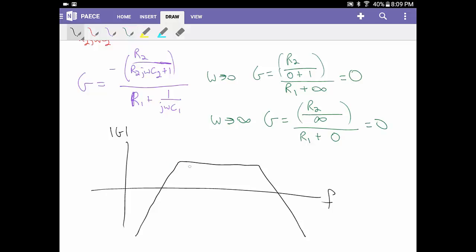Now, how high does the gain go? At what point are these low and high cutoff frequencies? That's for you to use the simulation tools that I provided you to figure out exactly what impacts what. So really play around with that bandpass circuit and see what actually impacts the overall gain, what impacts how wide this band is, and this week in lab we're actually going to be seeing the impacts of all of these, and we're going to be building and designing one of these bandpass filters.